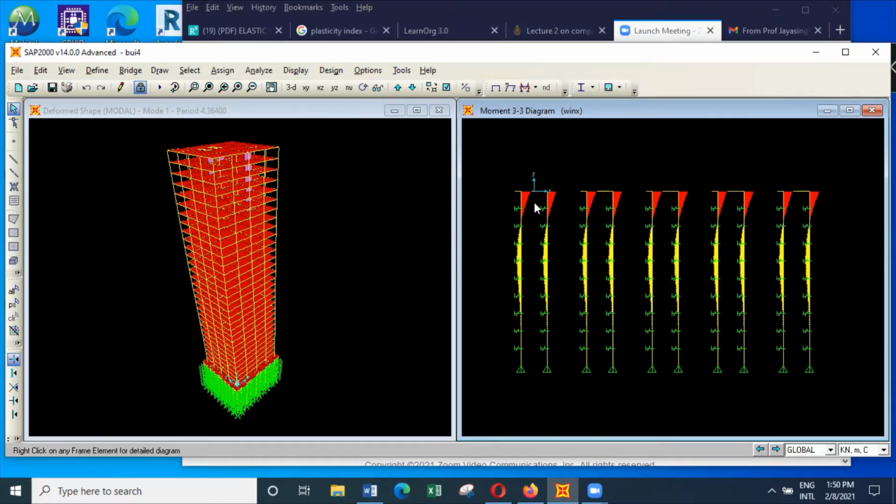The reason is these piles can actually resist the bending moment acting on the column by utilizing the axial force carrying capacity of each of these members. So that's why the bending moment on the piles will not be that critical. So basically, when you do the complete modeling like this, you can get many useful information.